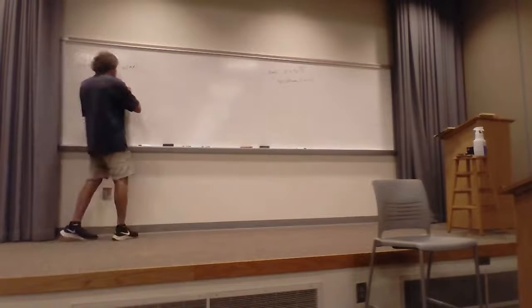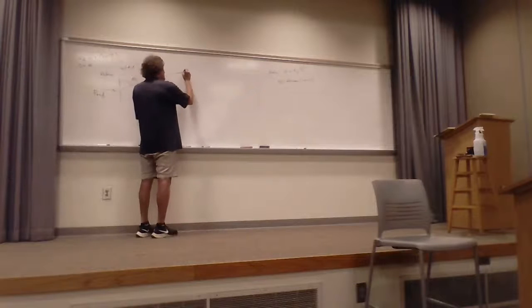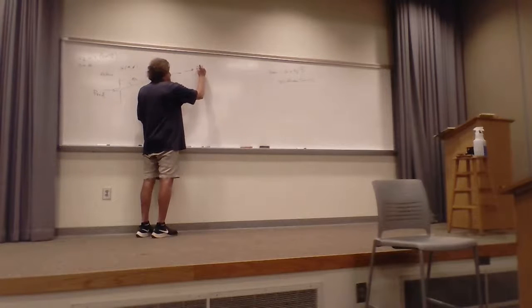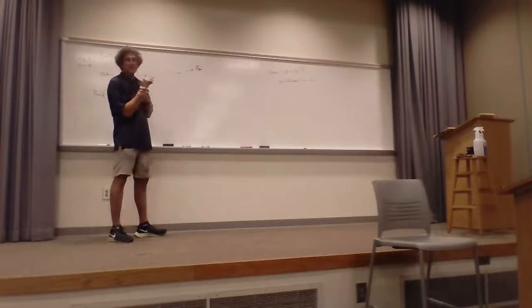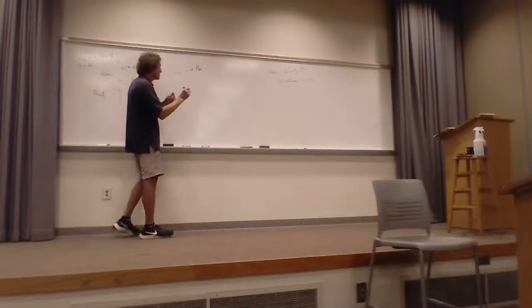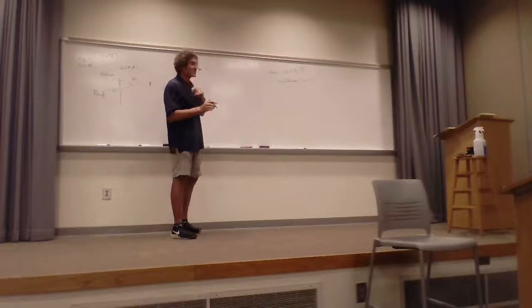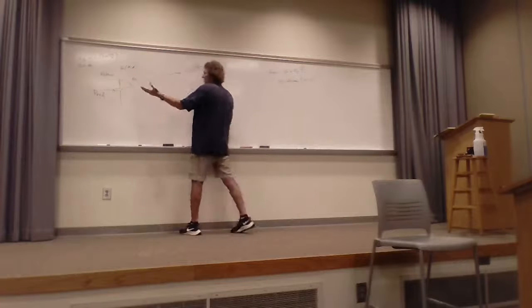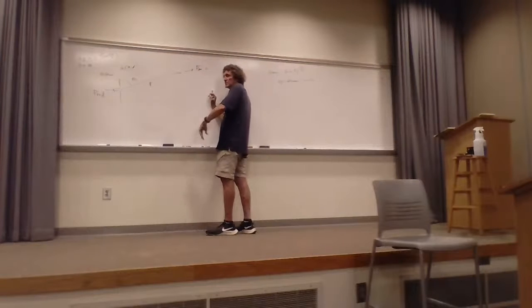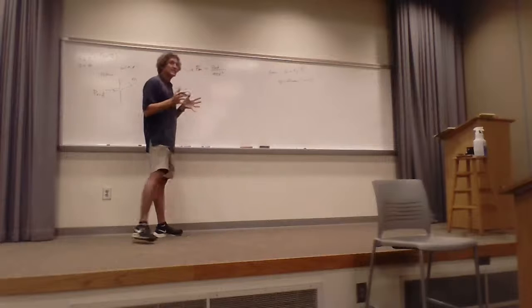Then, if I want the power density at any given angle, theta and phi, I'm only going to show you theta. If I want the average power density radiating away from the antenna, assuming it's at the origin and this is far away, then I can assume it looks like just an isotropic radiator to start with. If it's an isotropic radiator, the power is radiating equally well in all directions. And if I want the power density, I just take the total radiated power and divide it by the surface area of a sphere, or 4 pi r squared. That would be the isotropic power density.